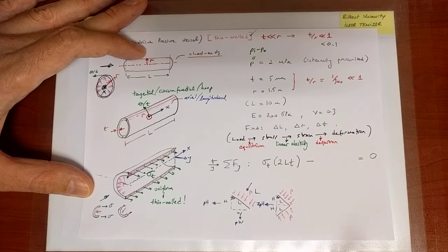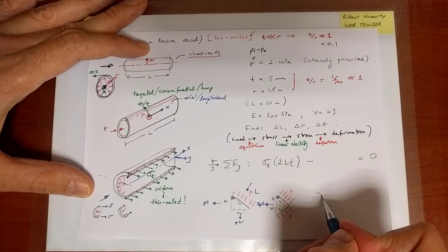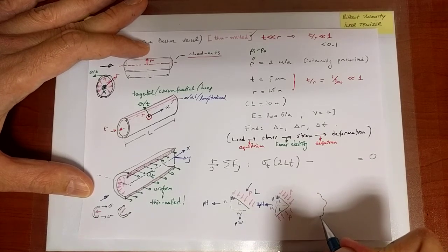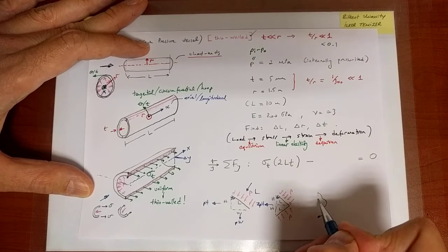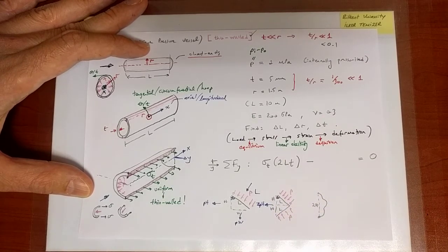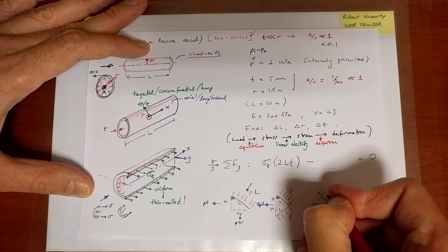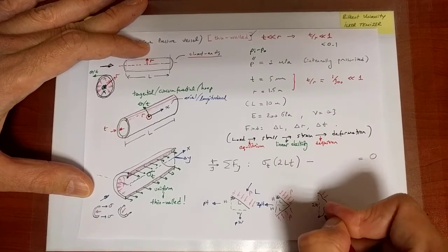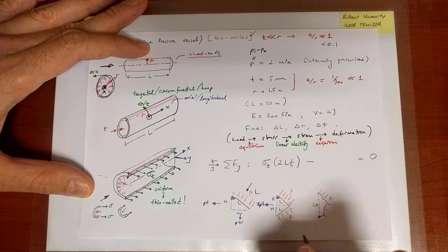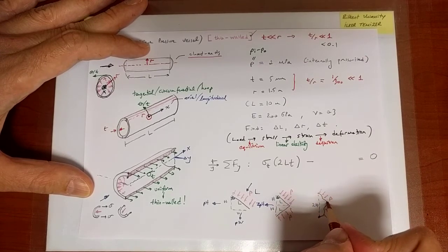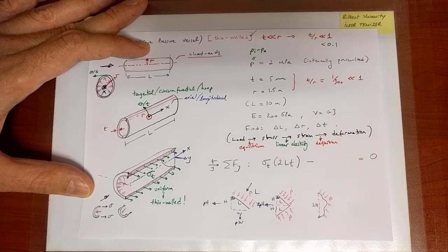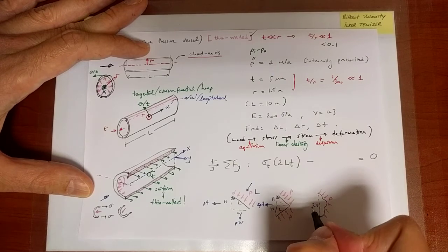So it turns out that it doesn't matter what the surface looks like, as long as you have one point connected to another through a height 2h, let's say in this case, and if you have pressure acting on that surface, irrespective of that shape and irrespective of this length, the net force along that direction is always going to be 2ph.